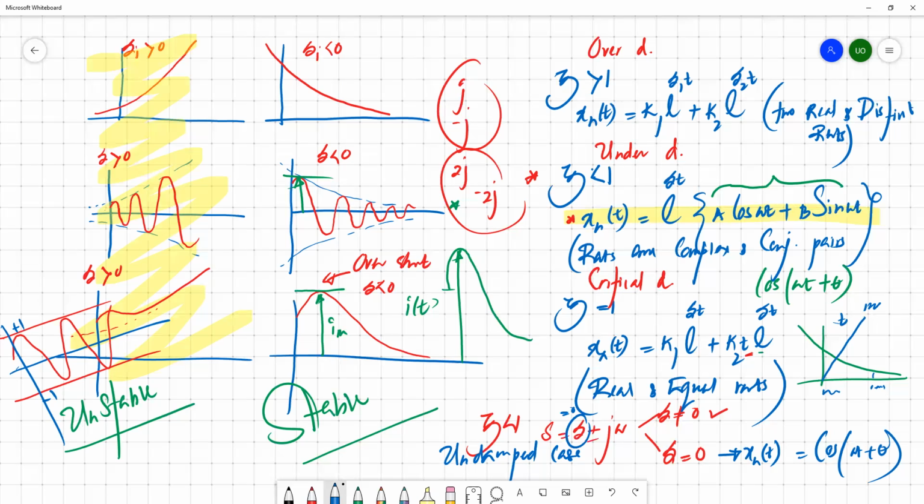If it is an undamped scenario, you know that it's a special case of underdamping. So then your response is something like a cos omega t plus b sin omega t. You can take these responses without deriving them, but you have to get the roots of the characteristic equation. Then you should clearly mention whether these roots are real and distinct, real and equal, complex conjugates, and so on. Then you can take the format of the natural response immediately and find the unknown coefficients.